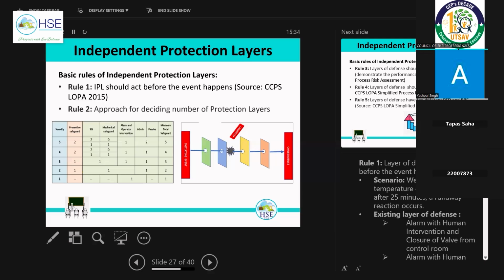Again, going back to the same example, monitoring of the reaction and recording the temperature. In case of other events, like alarm response, there are a few standard response times we consider, mainly in quantitative risk assessment. In case of a shutdown system or control system, we have the control valve and transmitter. In case of an increase in temperature, the steam supply valve closes. That is the shutdown or control system. Normally we consider a response time of maximum 2 minutes.